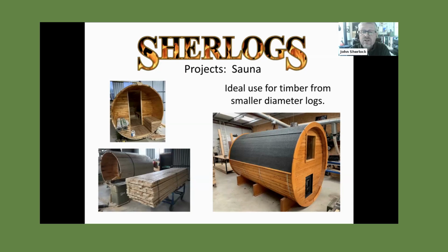And if you look at the 3 feet on the bottom, we made them out of Douglas fir. The reason we made them out of Douglas fir was, number one, the sizes we had suited, plus we consider it a little bit more durable. And at the very bottom of it, we put 3 little horizontal, little flat, what I'd call feet. Therefore, if the timber eventually decays, they can be sacrificed and new ones put in. We still make some of them. If we go on to the next one there, Maureen.